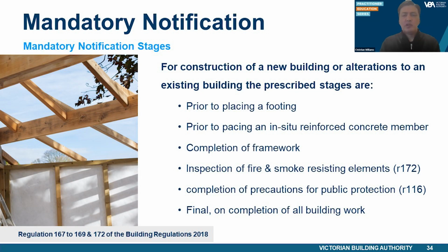For construction of a new building or alterations to an existing building, the prescribed stages are before placing a footing, before pouring an in situ reinforced concrete member, completion of framework, inspection of fire and smoke resisting elements as required under Reg 172, and final on completion of all building work.